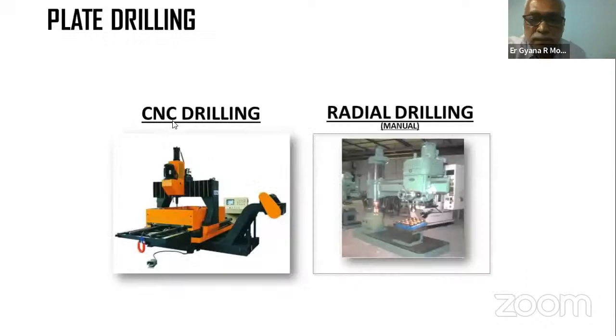Then nowadays, many of the clients are insisting on CNC machines. Earlier, there were many methods of drilling. We had radial drills, we had magnetic drill bits. Even those are still in use today. And many fabricators are also graduating to CNC drills.